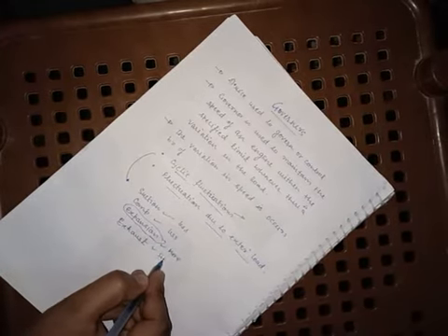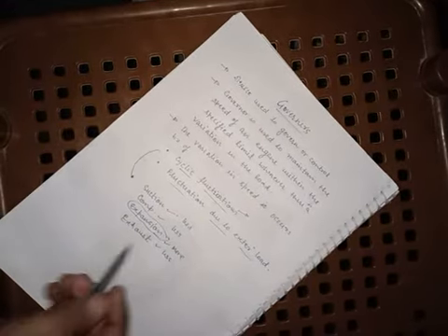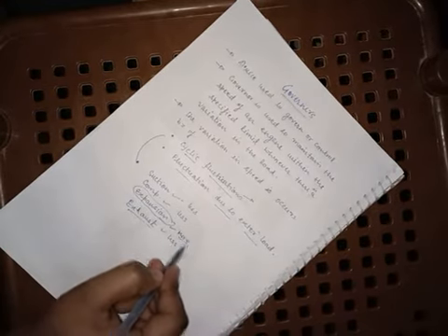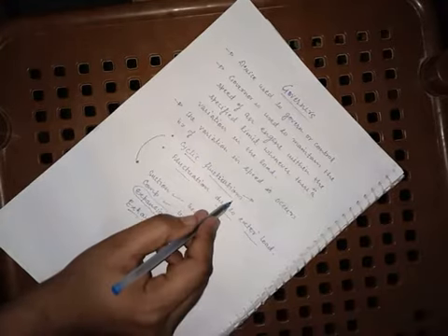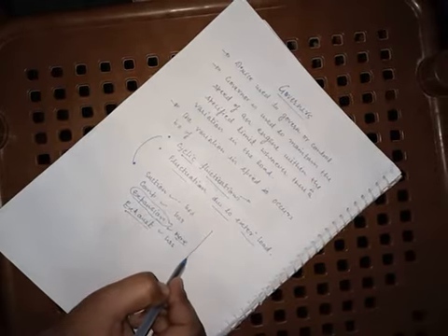So the exhaust, suction and compression strokes consume power, so the torque is less. In the expansion stroke the torque in the crankshaft is more, so due to this torque the speed increases. These cyclic fluctuations can be controlled by putting a device called a flywheel.